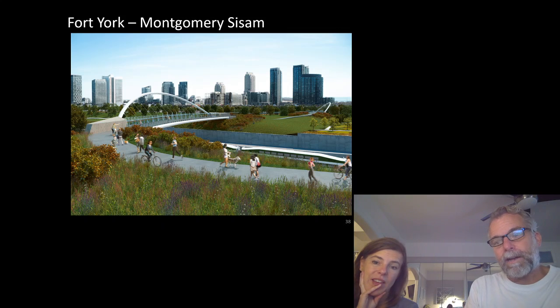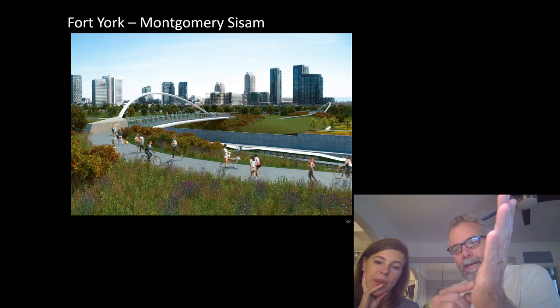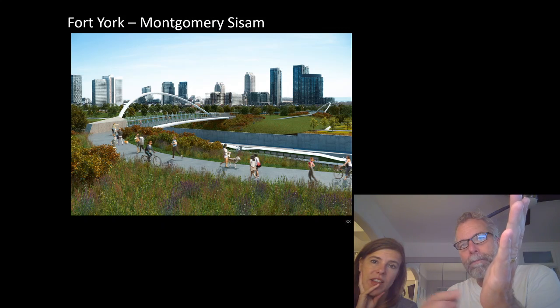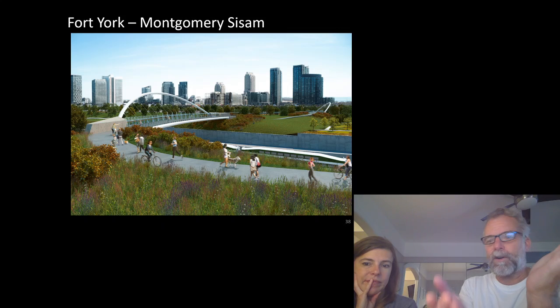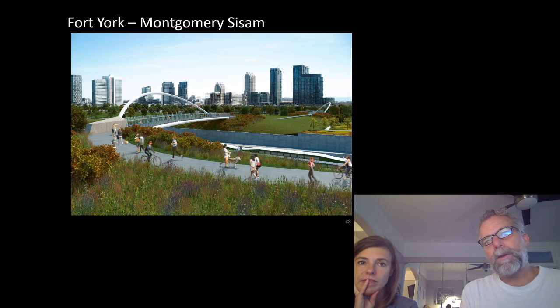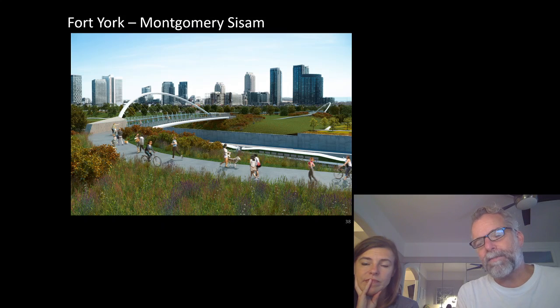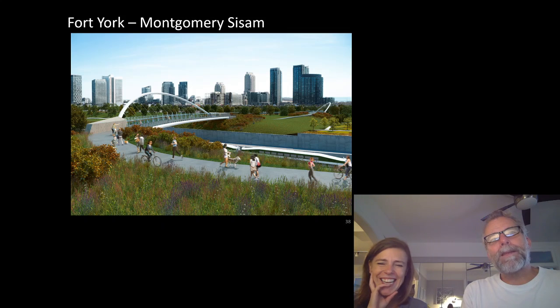This is a really unusual way to build this type of bridge. Often there are declined arch bridges, often with a curved deck, but typically the deck curves opposite. And the idea is that the eccentricity of the arch balances somewhat the eccentricity of the deck. We rationalize that the weight of the deck is small relative to the weight of the occupants, and so curving it to follow the arch wasn't a problem. And architecturally, and you analyzed it too. Well, obviously, yeah, we improved it, but